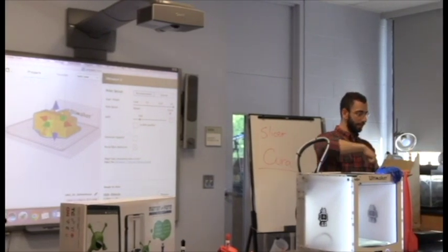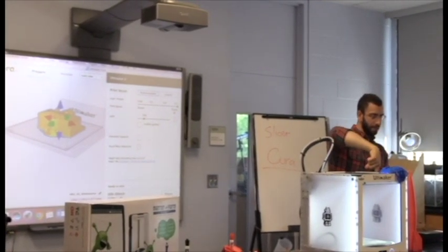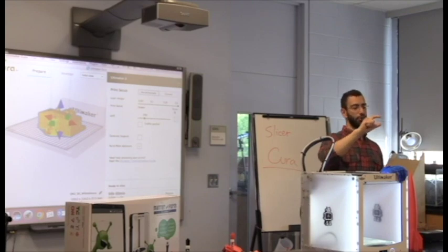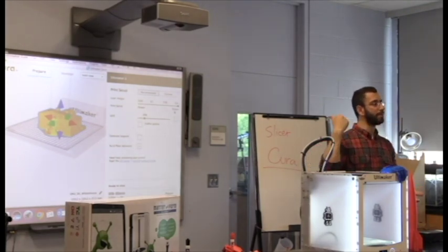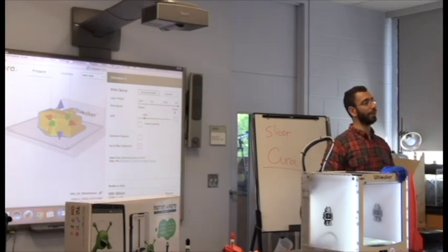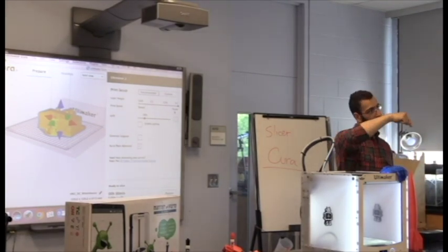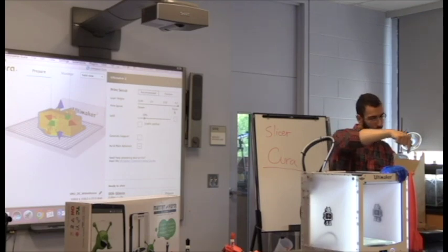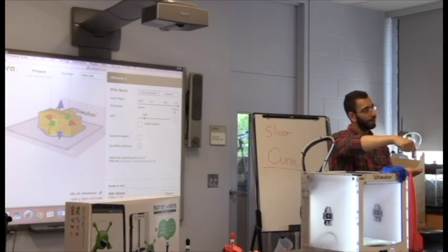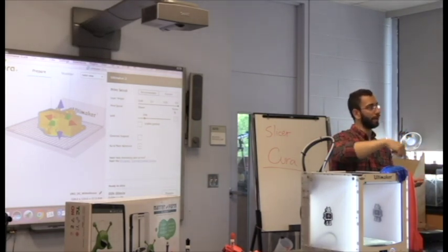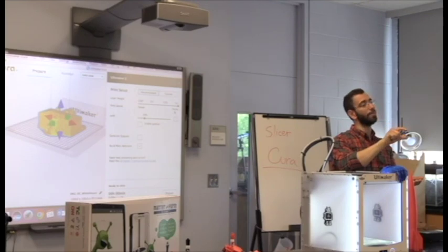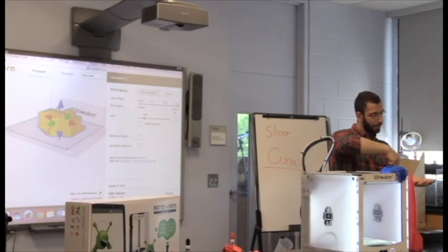And literally, if I'm trying to make a circle that's a millimeter in height, and I have it set at 200 microns each layer, and it's only one wall, assume it's literally a single line, it'll go around once, and then it steps up by 0.2 millimeters. Then it prints another one. We're already at 0.4, and it does 5 of these. By that, we're already at 1 millimeter. Okay, 5 of those, and then it's done.